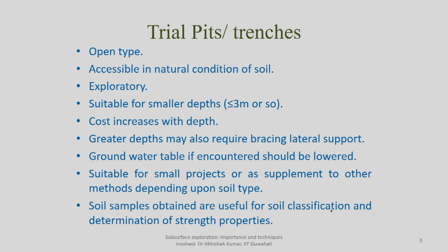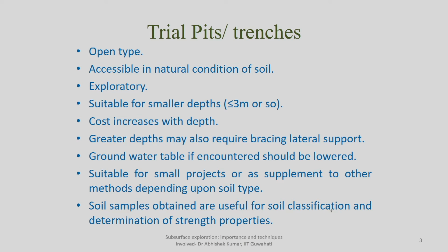It can also be used as a supplement to other methods. So, whatever soil type you are getting here will give you some kind of indication whether the same kind of soil is being found in other tests also. So, it is suitable for smaller projects as well as a supplement to other methods, depending upon what kind of soil is there. This method will give you what kind of soil actually exists at the site. Then depending upon what kind of soil you are encountering and what the strength of the soil is in terms of stiffness, you can get an idea of what kind of exploratory method you can go for, and whether the resources available for detailed investigation are sufficient to go for this kind of investigation at the particular site of interest.